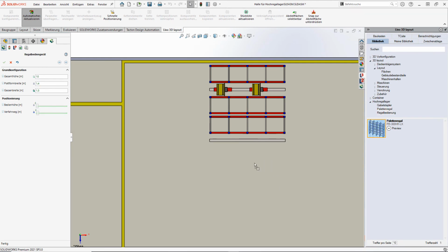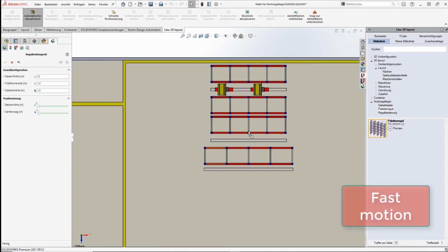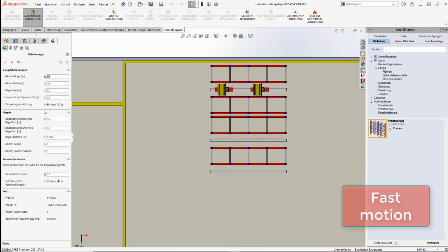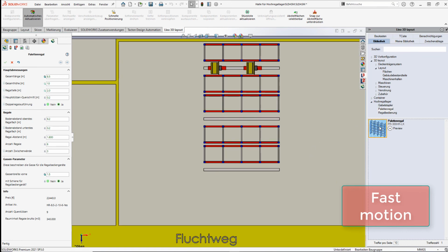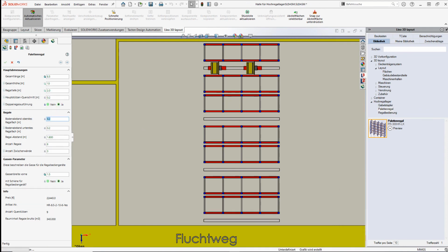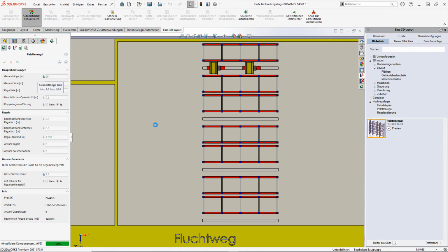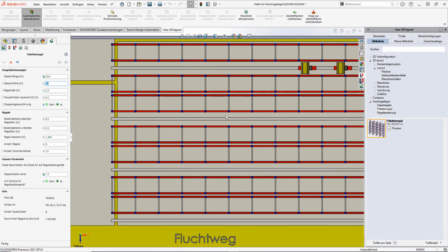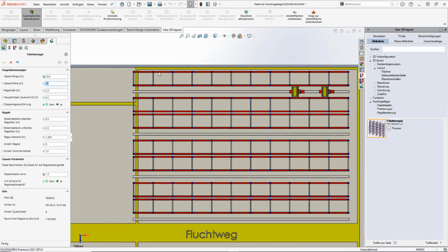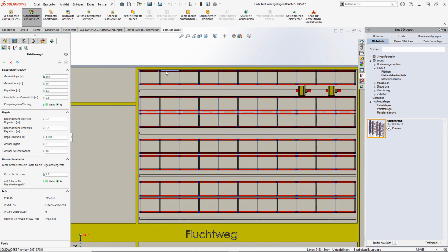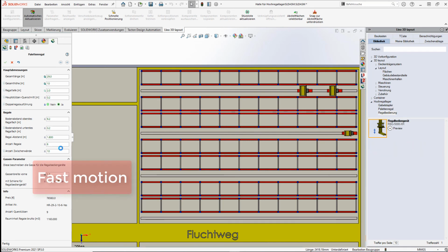We complete the quadrant at the top right and add more pallet racks. In the set direction, we have now used the space up to the escape route. Now it's time to set the right length. Okay, we can fill 29 meters here. This is only a mouse click with Lino 3D layout because the length is defined as a so-called chain global parameter. Let's quickly distribute some stacker cranes to the rows and simulate their positions.